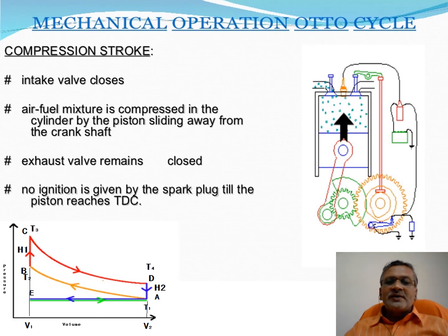The exhaust valve remains closed. No ignition is given by the spark plug till it reaches the TDC. This motion is shown from A to B on the graph.